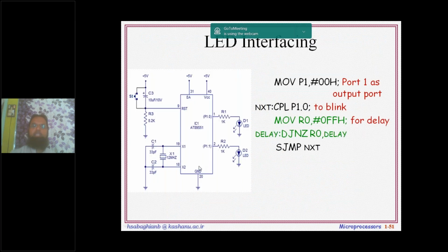Now see here, in the interfacing part, what you need to do is you just take 8051 and then take this connection. This is mostly required, without which there is no interfacing. You can take this reset setup or not, it is your wish, but you must and should take this. So what I am going to interface here is LED interfacing. I'm just connecting 2 LEDs to 8051.